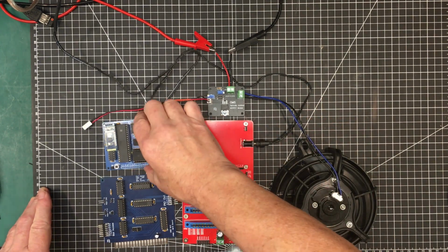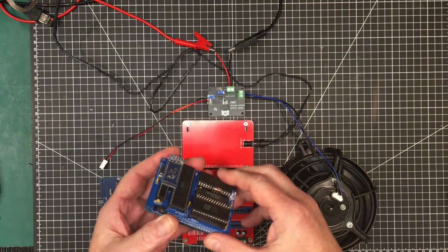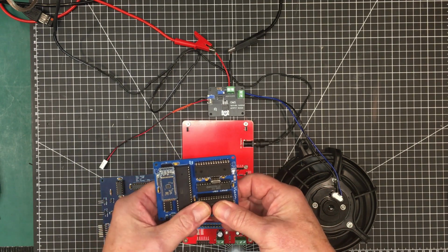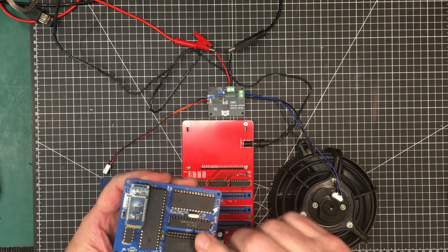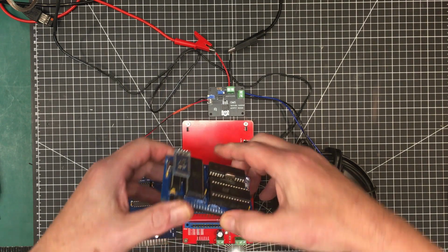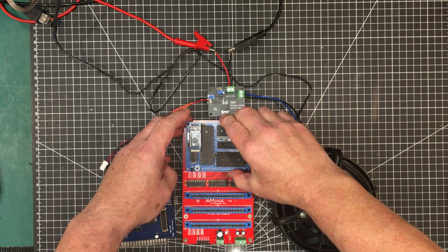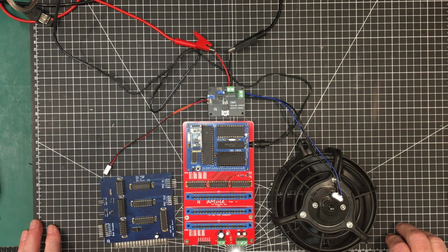So let me kind of show you how this thing works. This is just a little 8-bit computer based on a 6502. It's a design I put together maybe about 8 or 9 years ago. This particular model of it runs at 14 megahertz, so it's not too bad. It's got 32 kilobytes of memory, 32 kilobytes of ROM, a little bit of space in there for I/O.